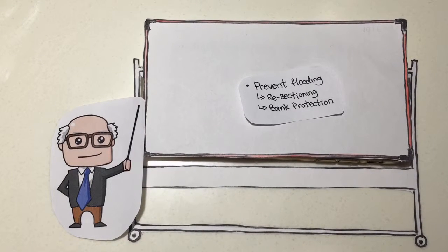For river resectioning, it is the widening and deepening of the river channel. It also increases the channel's ability to hold water, thus decreasing the chances of flood. River resectioning also increases the amount of surface runoff from the surrounding area into the river, because more surface runoff can now enter the river without causing it to flood. In addition, the riverbed and banks may be smoothened by replacing the soil of the riverbed and banks with cement and granite. By doing so, there's less friction between the water and the riverbed and banks. Thus, the speed of the river will increase and allow water to flow away from the area more quickly.